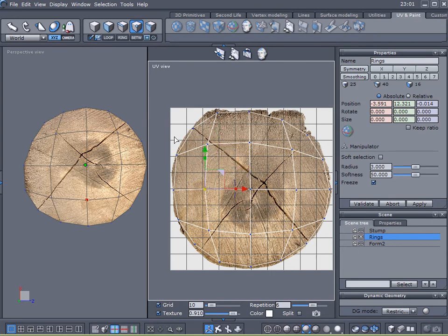But let's say this texture was a brick wall where it has very definite horizontal lines and very definite vertical lines. When you start stretching the geometry, there your brick wall is going to start taking on this characteristic, where that stretched part appears on it.